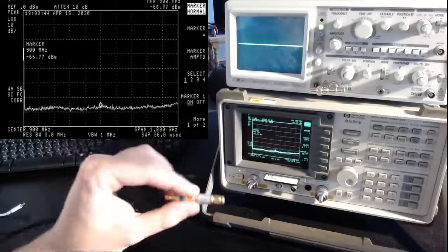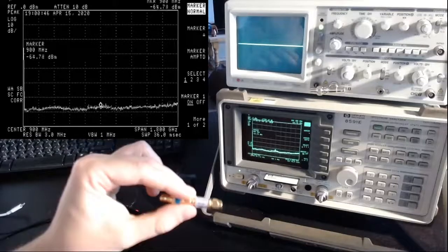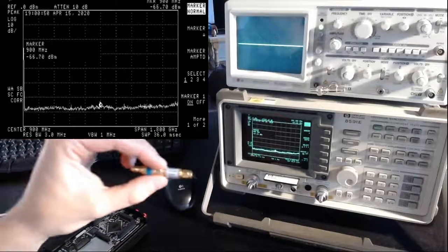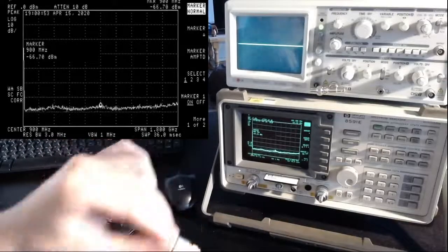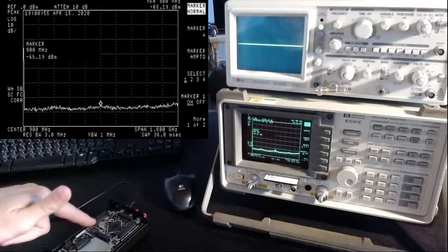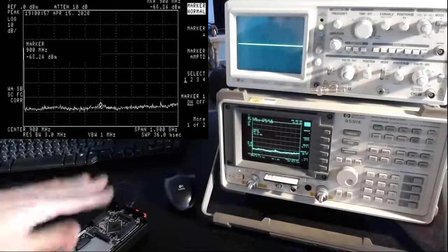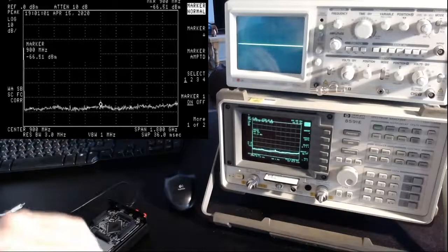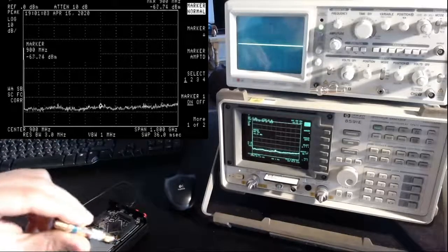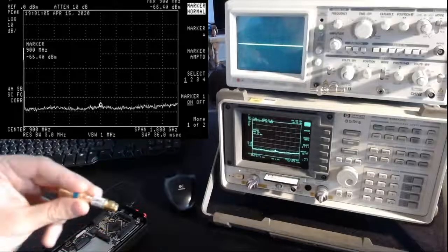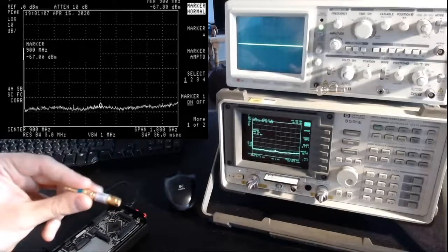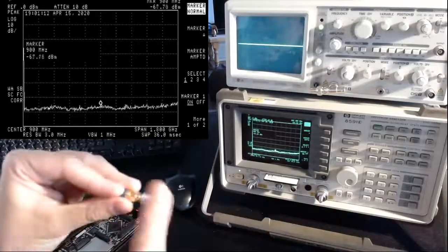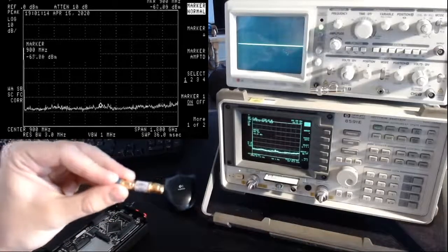The functionality of this little device is very simple. It blocks any DC component on the input. Ideally, the HackRF will not produce any DC component anyway. I mean, it's possible to add a DC component to the signal to activate some external antennas or external amplifiers. But this is not active at the moment. Anyway, I want to be super sure about that, so I'm adding this DC blocker.